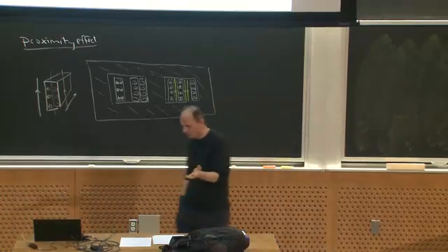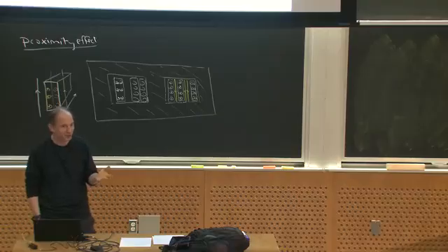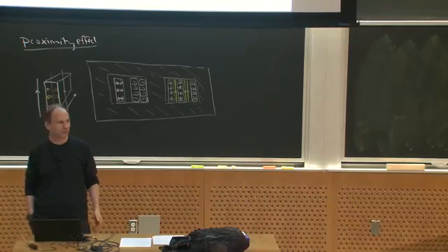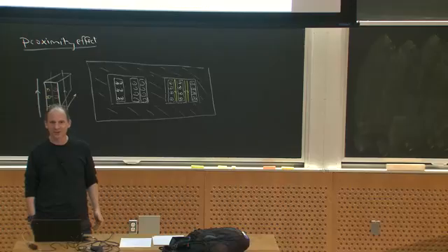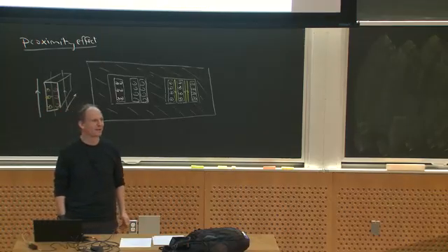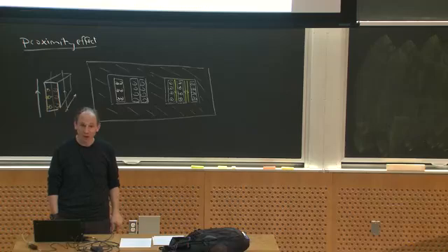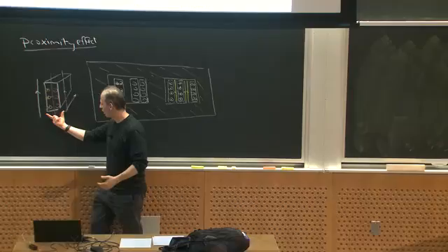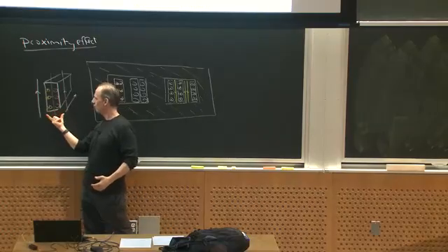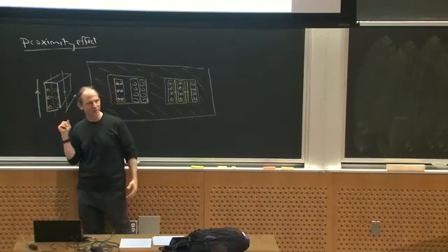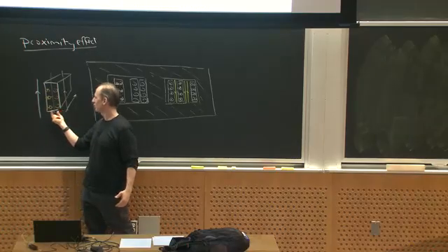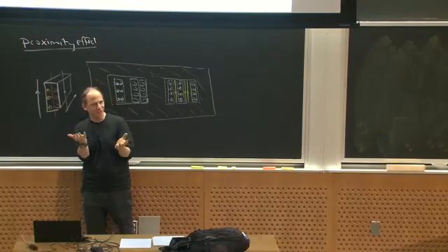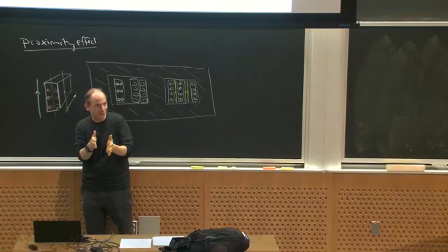So that's just a warning, because you can get into this weird situation, I've been there, where you think, oh, my conduction loss is too high, I'm measuring it, I've got too much resistance, so what's my natural inclination? Put in more copper, use fatter wire. And you find out you put in fatter wire and the resistance goes up. The reason is that as you make this conductor wider, there's more room for the eddy currents to circulate because of proximity effect. If you make the conductor thinner, this current going this way and this current coming back kind of overlap and cancel, and you get less proximity effect loss. So sometimes it can be better to use thinner wire instead of thicker wire to get less loss in net.